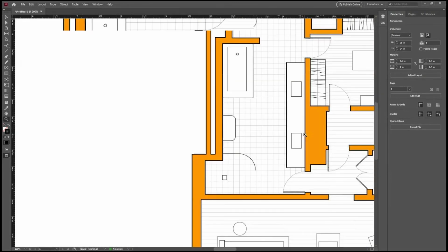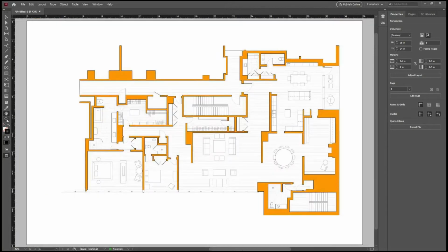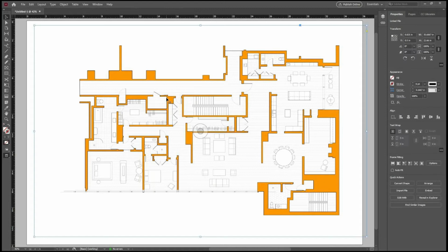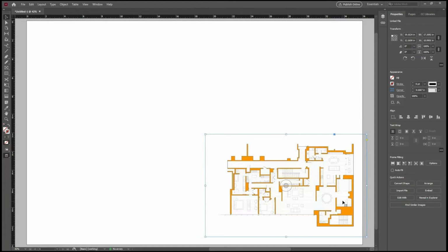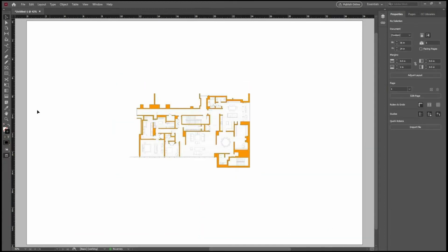Zoom in with the magnifying glass and make sure the quality is there. And the quality looks pretty decent. You expect these little pixels to show up here because this is imported from AutoCAD. Double click. So you can take these drawings and, selecting them with this tool, hold Shift and Control on the PC and drag that corner down, making this drawing smaller will make it better.